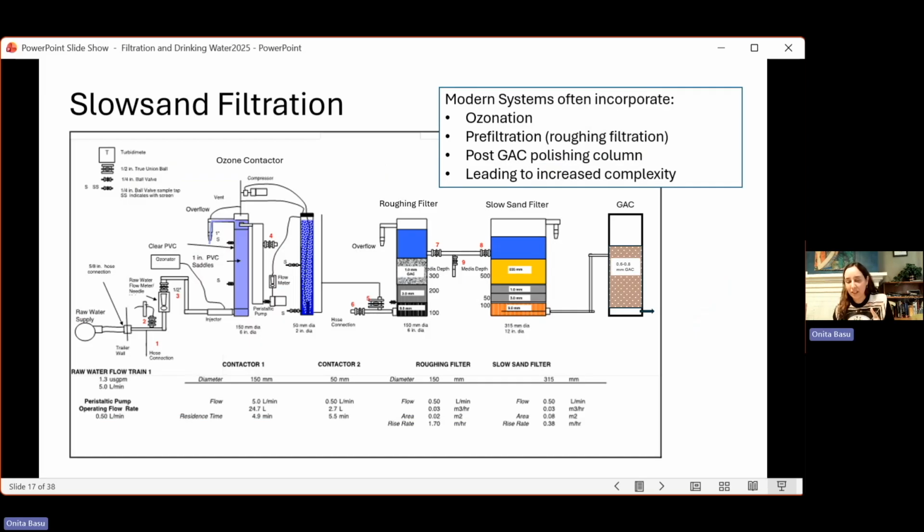Now, I had mentioned earlier that slow sand filters are both low tech and high tech, and here is where it becomes more of a high tech option. It's not uncommon, especially in Canada, to have slow sand filters in smaller communities. It's very useful in that smaller communities have larger areas. It helps ensure a higher degree of bacterial or pathogen removal from the system. The slow sand filter itself doesn't require a lot of operator interference on a regular basis. So that's the advantage of it.